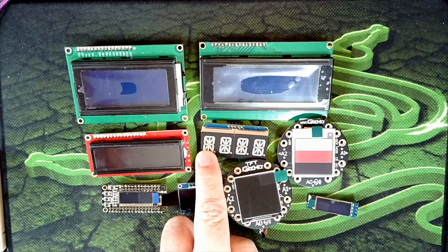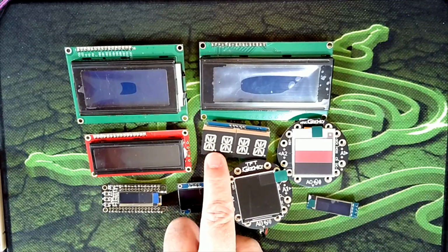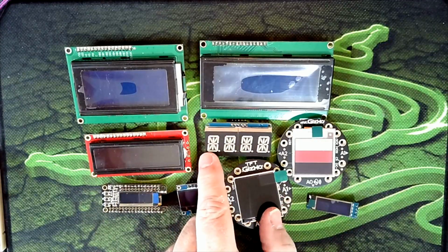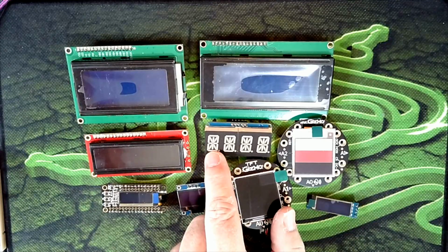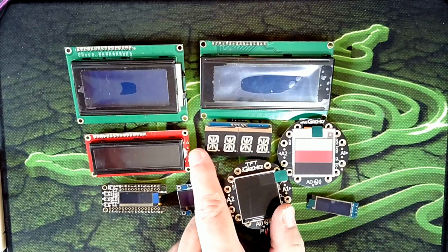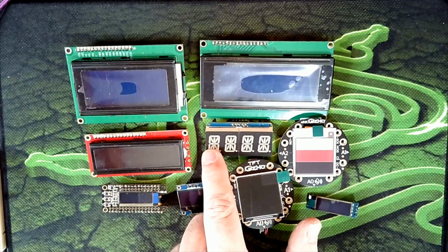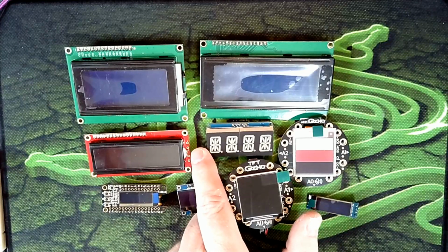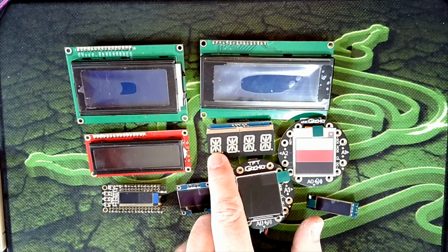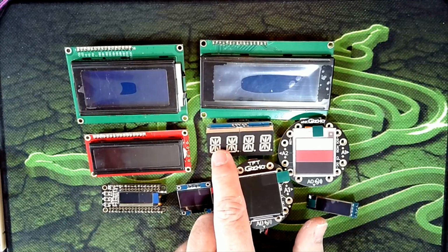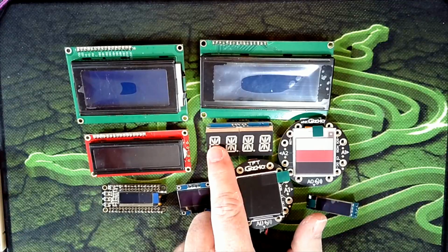And finally, we have numerical or alphanumerical displays like this one here. This is a multi-segment display. They make a 7 segments per digit. A 7 segment per digit will do just numbers, basically 0 through 9 per digit. This is 4 digits wide, but this one, with all the extra little pieces, has 13 segments in here. You can do alphanumeric as well as some symbols. You can do arrows, you can do a few different things like that, so you can actually create some different features. But again, these drop a fair bit of power because they are LEDs that are lighting it up inside.